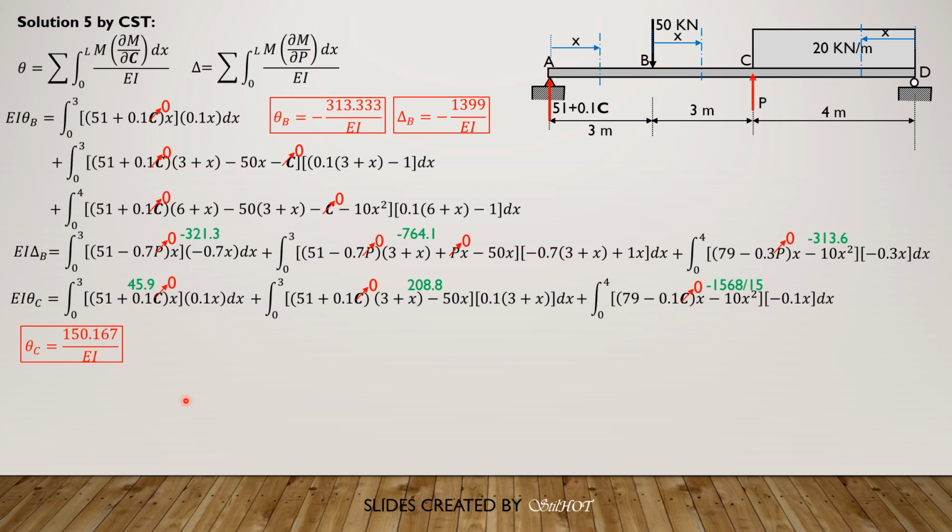Then finally, we remove the loads and the reactions, replace it with an upward force at C, then this will be the result. Due to P, the reaction here is downward, so it's negative. So it is P times 4 divided by 10. So you have to subtract 4 over 10 of P, or negative 0.4 P. Reaction at the right is 79 minus 0.6 P.